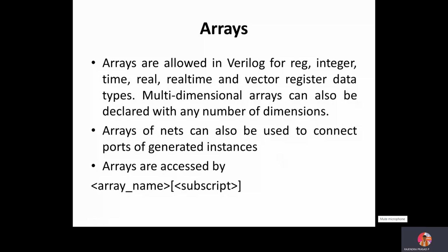Good morning, friends. Today we'll be discussing one more basic concept in Verilog, which is arrays. So how are we going to declare arrays in Verilog? What is an array? Arrays are allowed in Verilog for register, integer, time, real time, and vector register data types. Multi-dimensional arrays can also be declared with any number of dimensions.